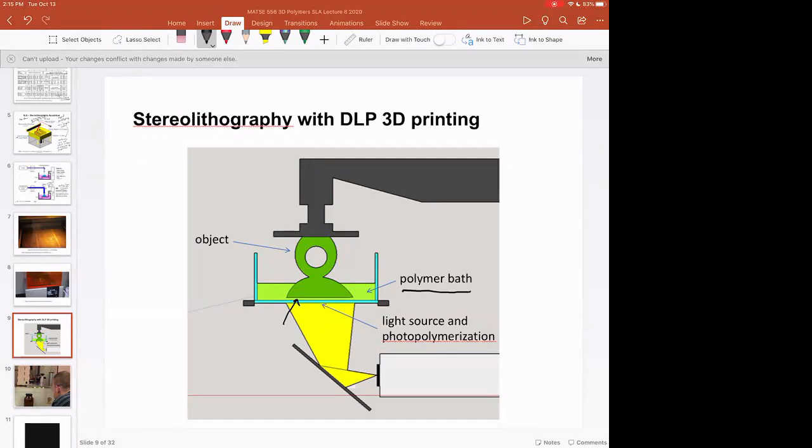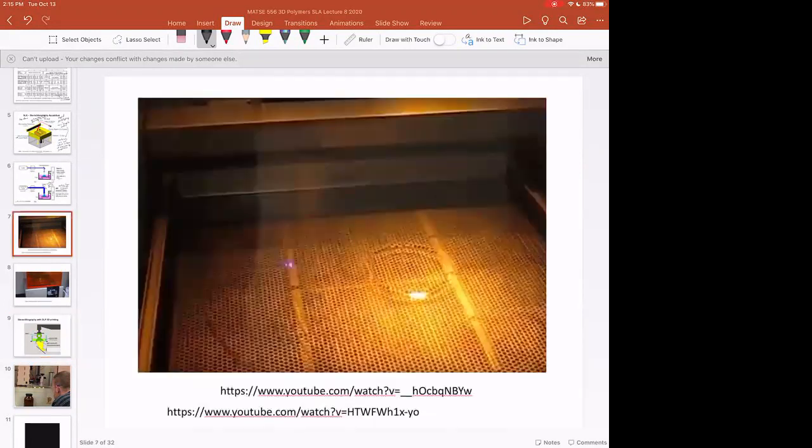So I guess from a layer height standpoint, does the slide 7 image have any, is that going to vary layer height, or is it still going to be regulated or able to be regulated to the same degree as slide 9? Yeah. Like, is it going to be a dead on 50 microns every time? Has it been 100% calibrated, or is a high viscosity or high surface tension liquid going to have cupping on the top of the part?